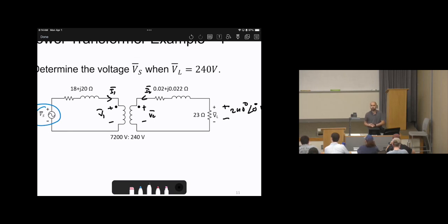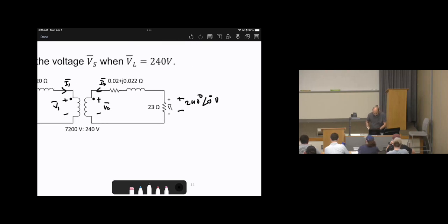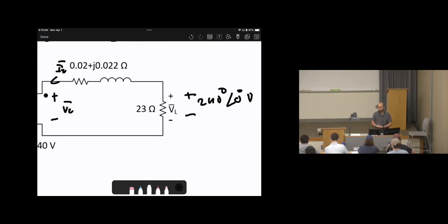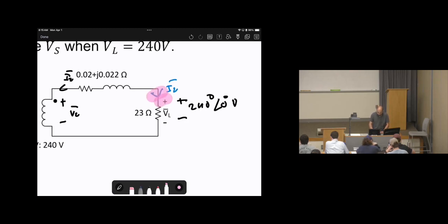Then start from the extra given information, which is the load voltage and the load impedance. How can we use this? We know the voltage, we know the impedance. We can find the current using Ohm's law. Is this correct? Yes. In order to apply Ohm's law here without going through the negative sign of Ohm's law, I'm going to assume the load current enters the positive terminal, and then I can guarantee Ohm's law will be positive. Again, I don't want to be confused about whether to put a negative or positive sign in Ohm's law. That's why every time I assume the current enters the positive polarity of the voltage. That's why I assume my own current. Then after calculating IL, I can find I2 from the relationship, if they are in the same or opposite direction. I just put a negative sign or 180 degrees phase shift.